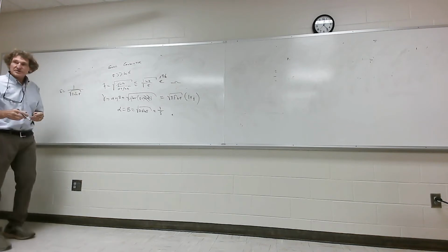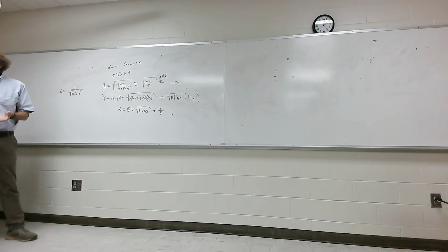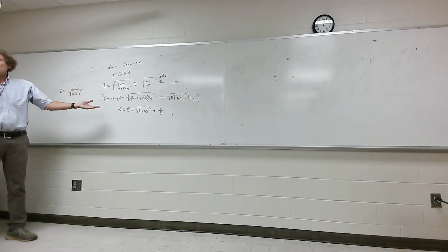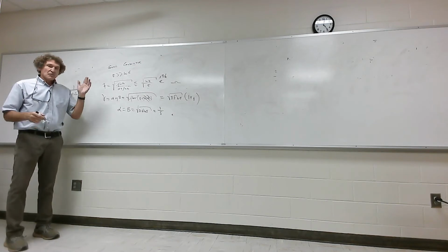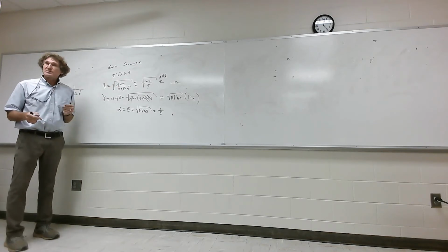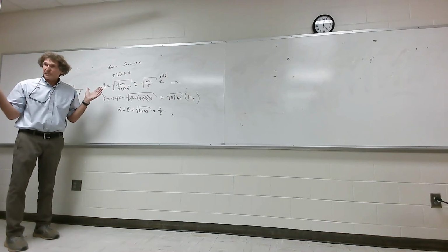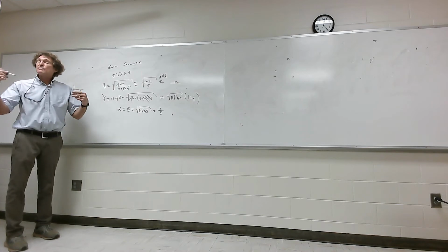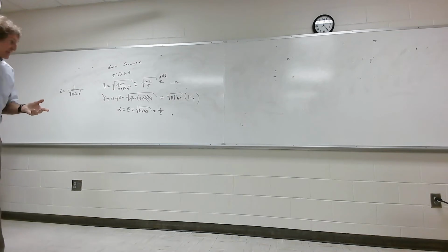And I'm just putting it here so you at least will have an appreciation for the reasons why I'm doing this. Here are the formulas. The reason I'm doing this is to bring it to your attention so you don't make silly mistakes on the exam. Now, if you ever see an equation where the real and imaginary parts of the exponential argument are the same times z, you know right away it's a good conductor. Y'all follow me? Anytime alpha and beta are the same, it is a good conductor, and from there you can proceed, assuming that, and it makes life a lot easier. All right, now that's true for these things.